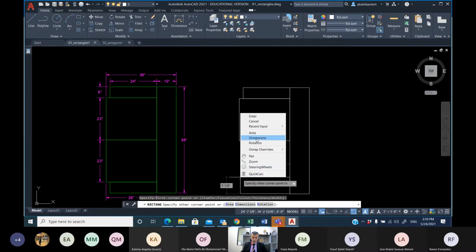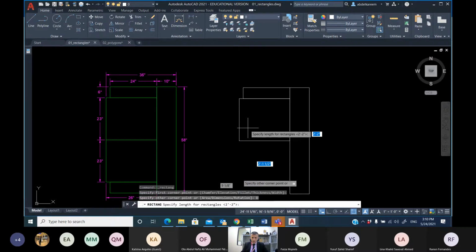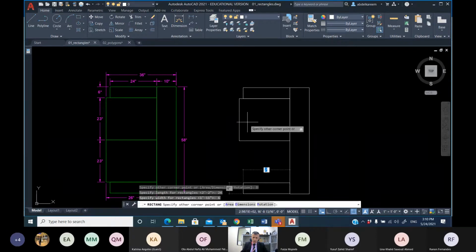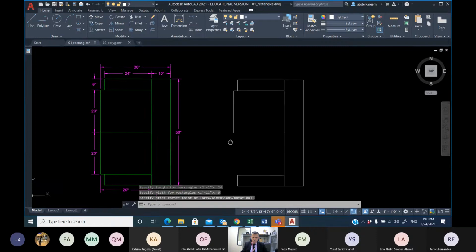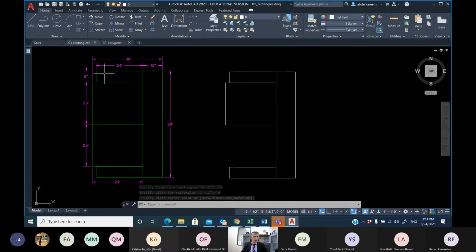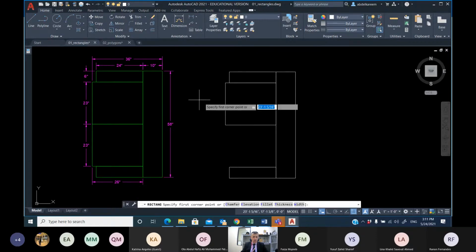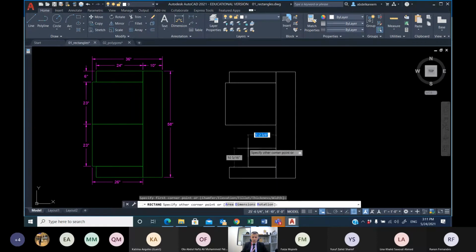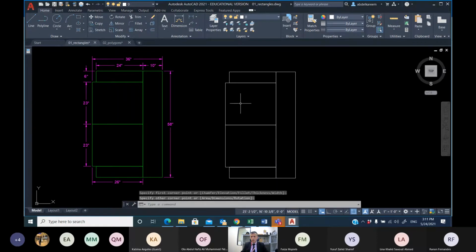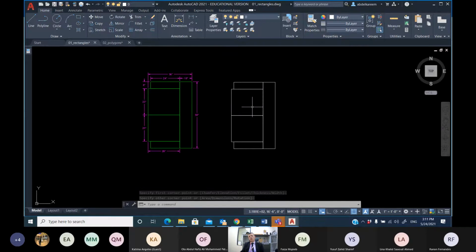Right click. Of course, we'll learn a faster way once we reach the modification today, inshallah. We will be doing things in a much faster way because I will not only depend on drawing, but rather I will draw something and then modify it. So dimension again, and that would be width 24, length equal to 6, and this would be my left armrest. And then I will go with another rectangle to finish the seat. I can select this corner up until this corner or enter the dimensions. And this is how we actually draw using rectangles.